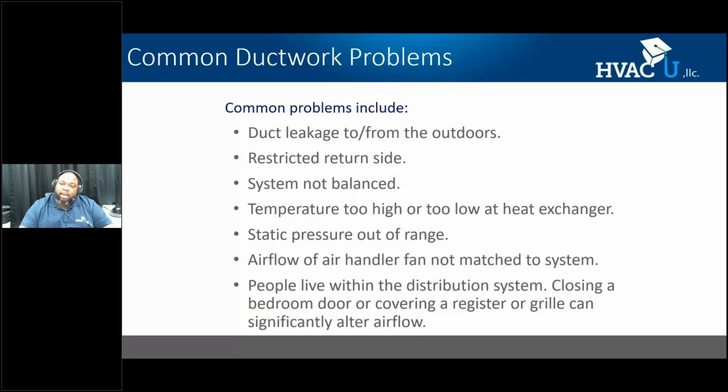Here are some common duct problems. We have duct leakage, which can leak to the outdoors, which is a significant penalty. We'll talk about that here shortly. We can have a restricted return side. The system cannot be balanced. We can have too high or too low temperature at the heat exchanger.